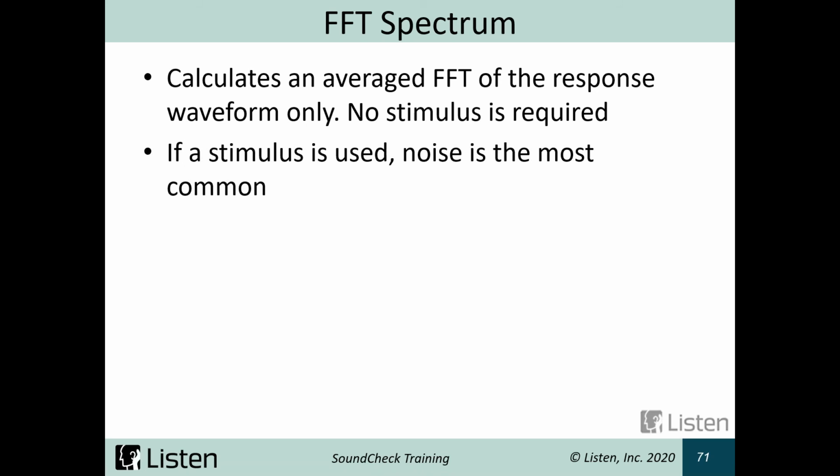If you are using a stimulus, then most commonly you could use noise. But no stimulus is required, or any stimulus could be used. We could look at an FFT of a log sweep, of multitone, of a step sine sweep, of an intermodulation sweep. It doesn't matter. It's just going to take your response waveform and run an FFT.